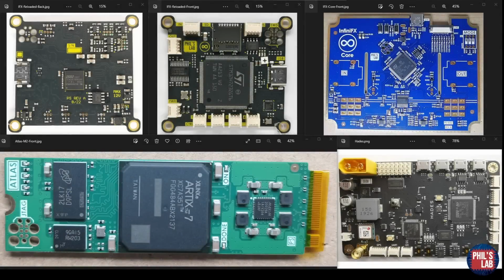In this video, I'll show you how you can get your PCB and hardware designs manufactured and assembled. We'll go through which files are required and how you can generate these files. For example, for manufacturing, we'll look at Gerber files, we'll look at how to generate stack-up information for controlled impedance and so forth, but also looking at the assembly side. What files do we need, such as bill of materials, component placement files, assembly drawings, how we create those, and which ones we need to send to the manufacturer, and which ones may be optional.